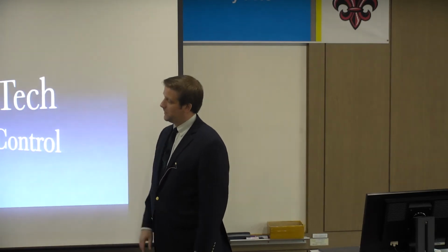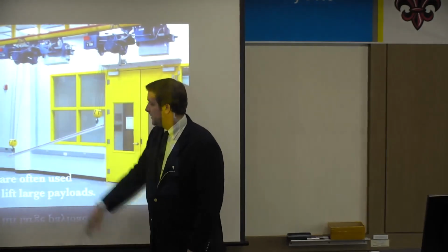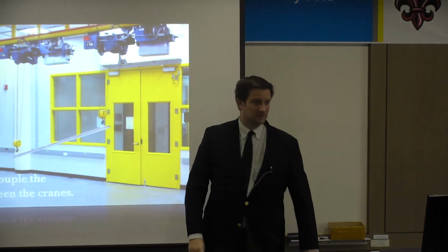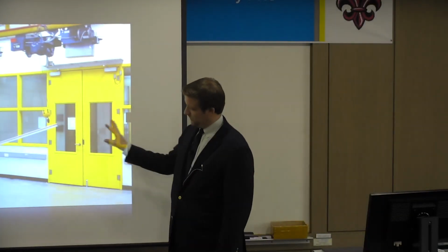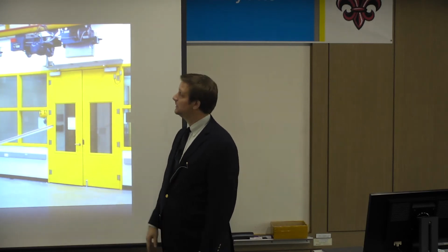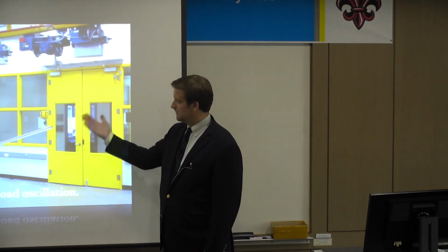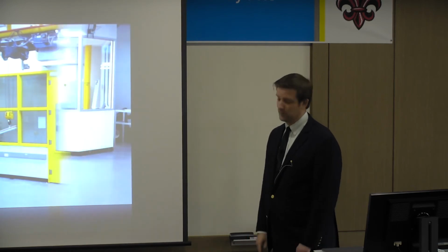So actually this is some work I did when I was still at Georgia Tech too. So you see I'm moving these two crane trolleys together. And in this case we only get one mode because it's a 4-bar linkage. It's pretty straightforward. Even a simple move like this can get you some vibration. And we can apply input shaping to that and get basically no vibration. Pretty straightforward, nice simple result.